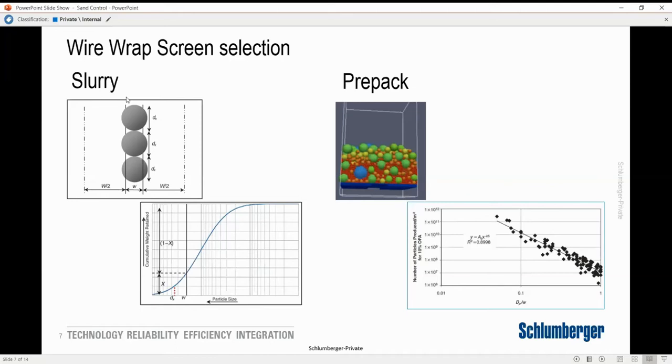Slurry options give you a bit worse, I would say. So it's purely up to the operator to select which option to go with. Most of the time people in our industry are oriented to go with the worst-case direction. So most of the time you will look at the slurry options, because you never know if the open hole will collapse gradually or in just 1 second.